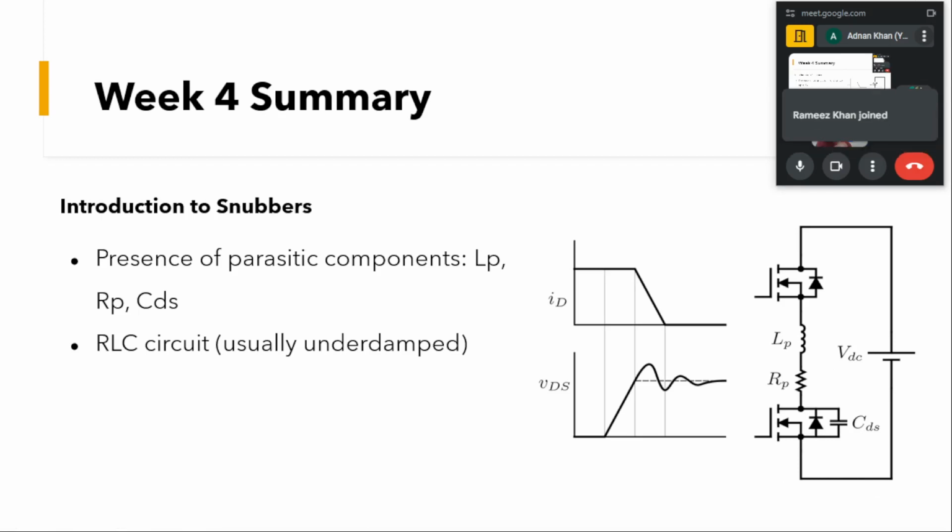But here, what is being done is, these parasitics have been lumped. What we assume is, all these parasitics have been lumped here at one point. And what this will cause, this RLC, if you can now see, we have L, R, and we know we have some capacitance in the device itself, between the drain and source, and what it forms is an RLC circuit.